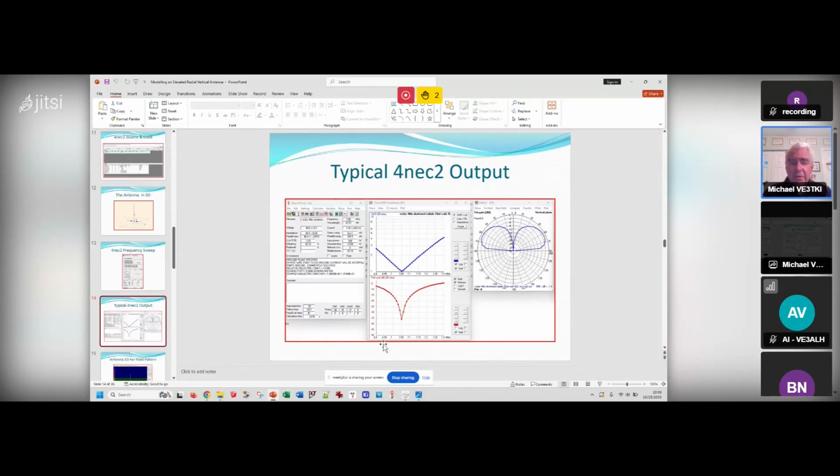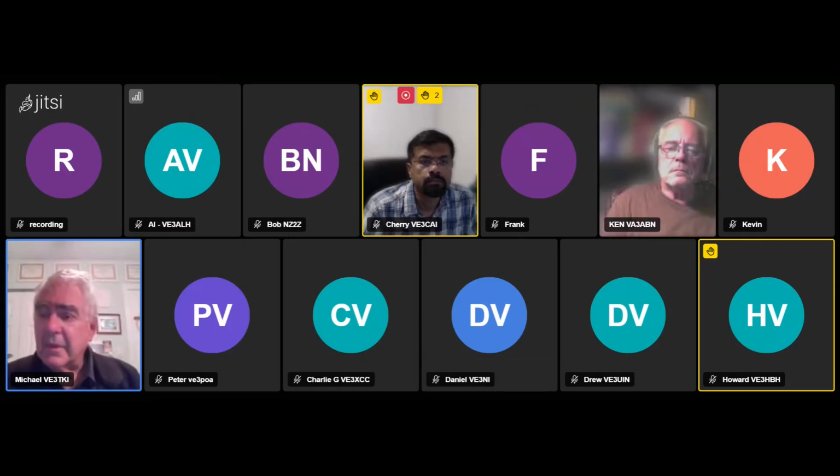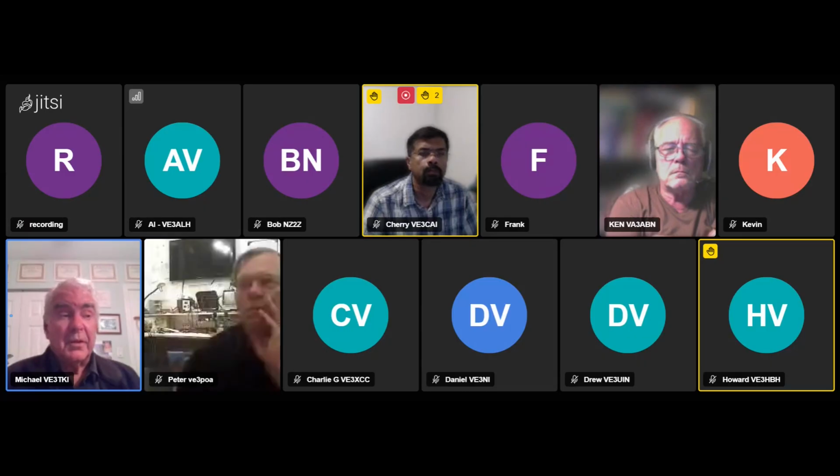If you need an extra 10 feet, you have one piece of 5-foot ladder line, and you join the two conductors at the top, and now you've got a single length that's the right length. And I just used, again, the elevated radials 3 feet off the ground. That's all I did.